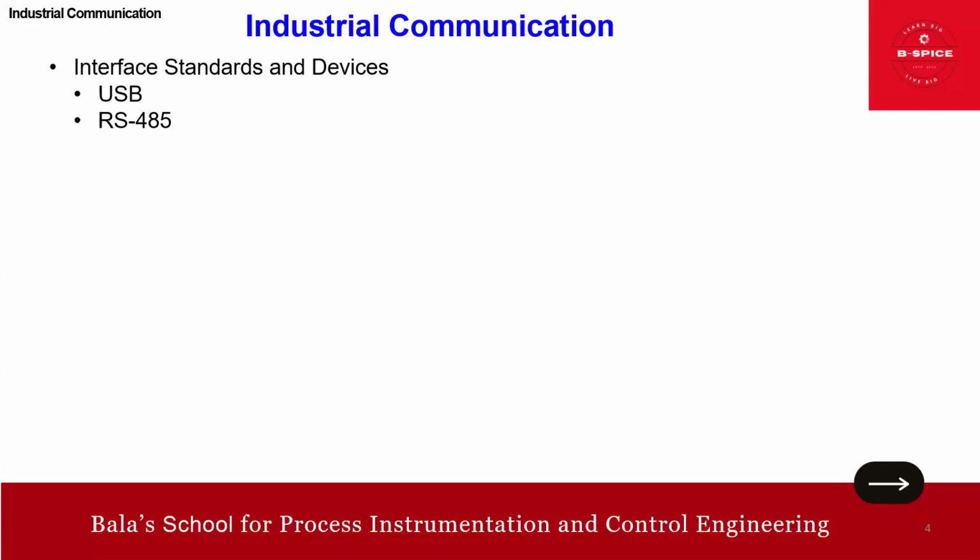The shorter the total length, the faster the speed, and vice versa. The longer the length, the slower the speed. And at an RS-485 terminal on a conductor, a small negative voltage represents an off bit and a small positive voltage represents an on bit. That is how the mechanism works.